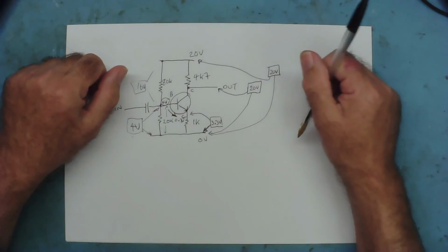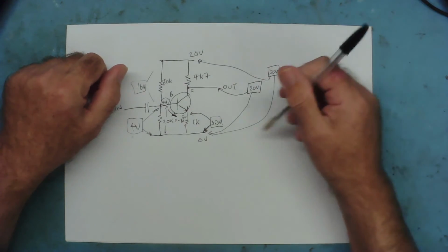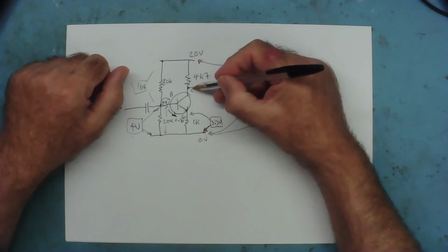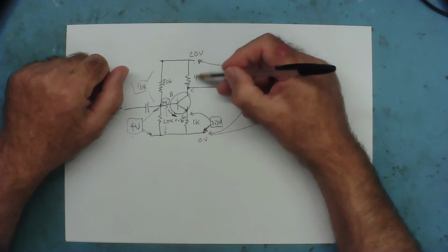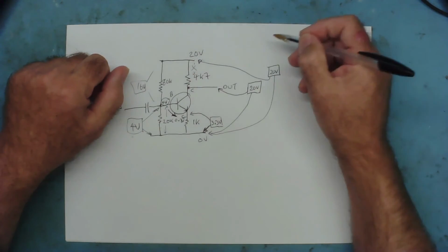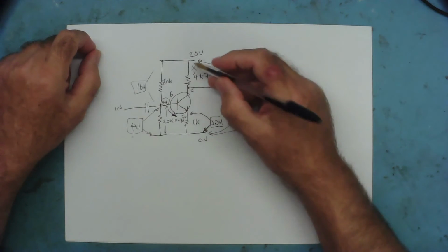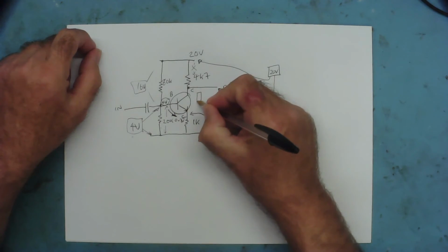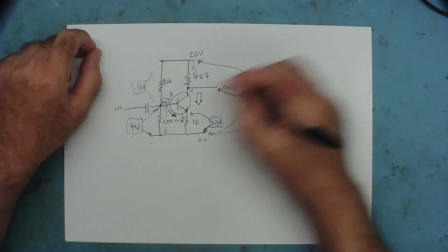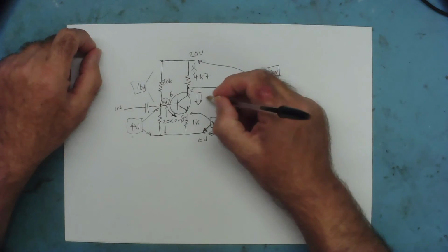The transistor's turned on. What's on the collector? 20 volts. Well, if there's 20 volts on the collector, it can't be turned on. The fact there's 20 volts either end of this resistor means that there's absolutely zero current flowing that way. If there was any current flowing that way, there'd be a voltage drop. So there's no current flowing down through the transistor collector to emitter. We've got base emitter current, but not collector emitter current. And it's turned on, and we should have, and we ain't.